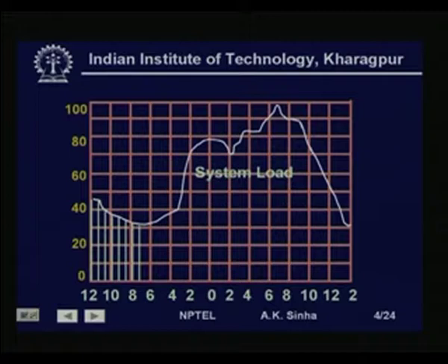So, in load flow analysis, we try to find out the voltages, the power flows and the power injections at various bus bars for any given operating condition. Therefore, load flow is basically a static network analysis problem for a power network.